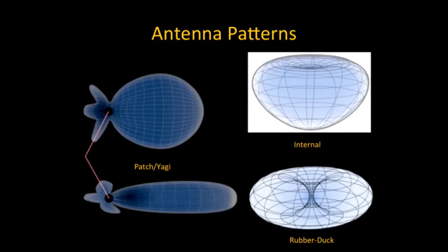So generally, your omnidirectional antennas that you find indoor Wi-Fi, they tend to have more of a cardioid type shape that you're seeing in the upper right. Your rubber duck antennas, those are the antennas that the aesthetics committee, again, particularly avoids, the ones that look like spiders on the ceilings. Then you can have patch antennas where you could place on a wall where you'd focus 180 degrees, your energy inside the building, and prefer not to send most of the energy outside the walls. And then for longer distance shots, or if you're trying to light up a long space in a warehouse, maybe between the shelves, you might use something like a patch or a Yagi antenna for something like that.